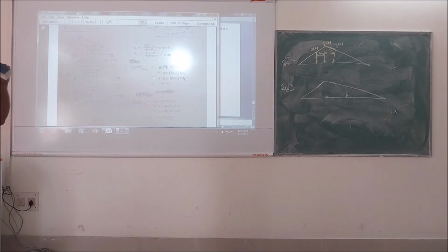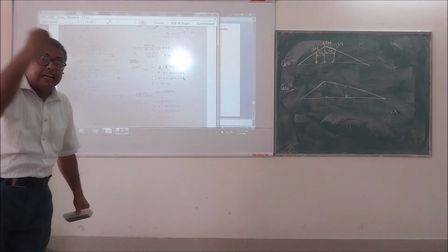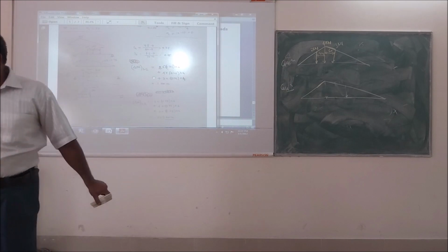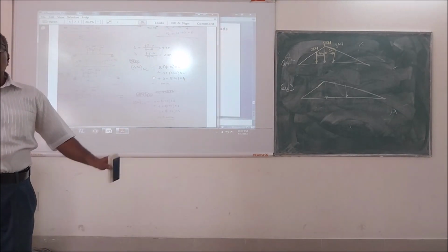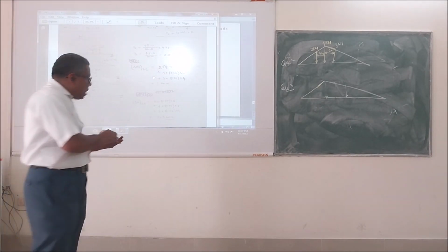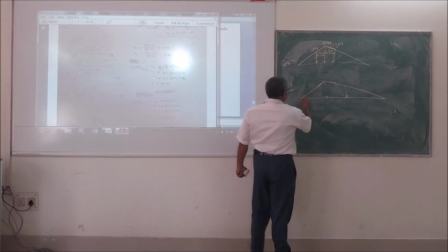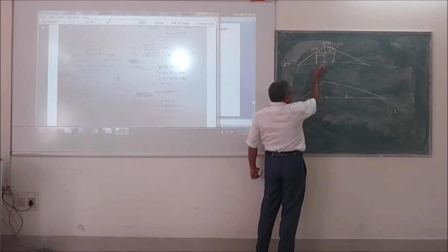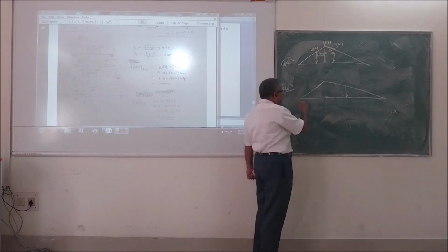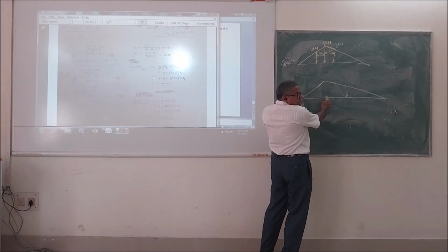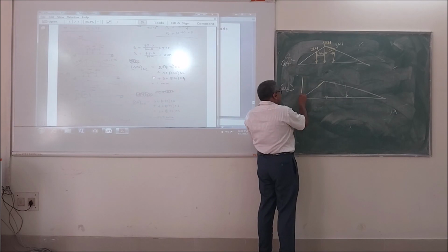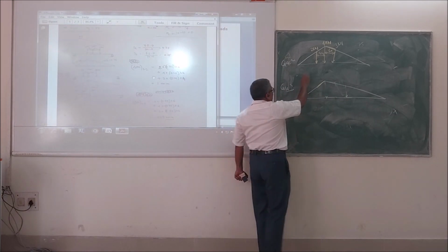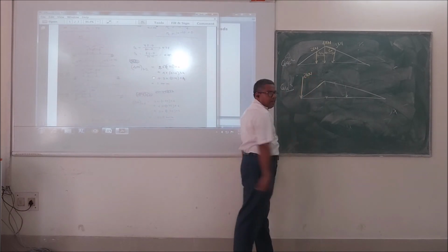So I think if you understand this, then any set of load series you can solve with changing slope load. Okay? So now the next position you have correctly said. This distance was 4 meter, right? And the next 6 meter movement will happen. So in total this distance is 10 meter we have taken. So that means this load will come over here. So now 2 kilonewton load will be placed over here.